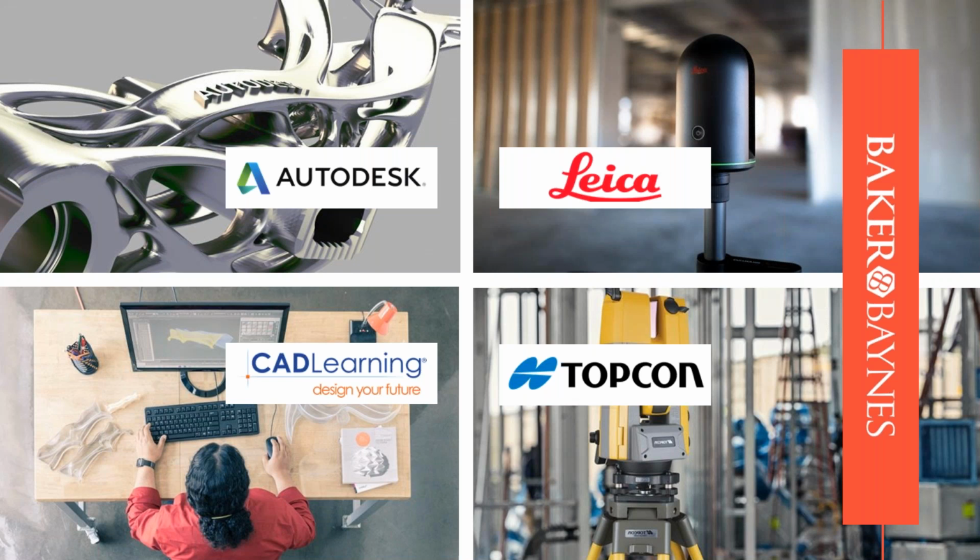So this one here on the top right hand corner, we're going to be actually looking at that. It's a 3D laser scanner, predominantly used for interiors or by architects. It has a range of about 60 meters and really good, 360,000 points per second. Really good machine, very simple, very compact, very easy to use.